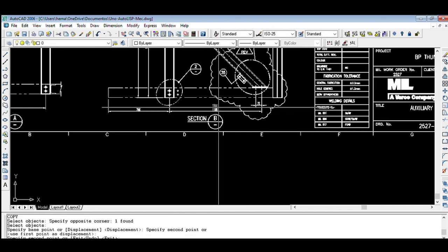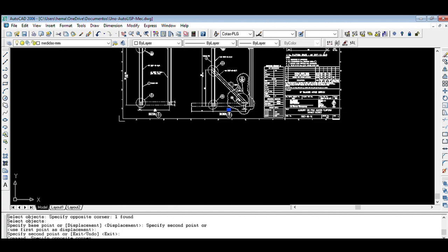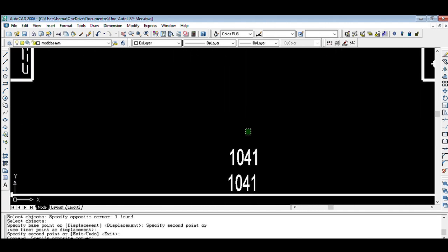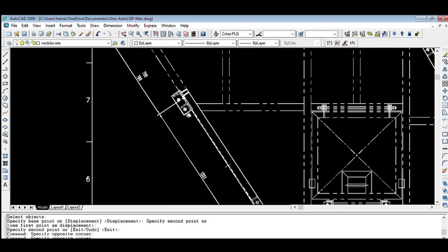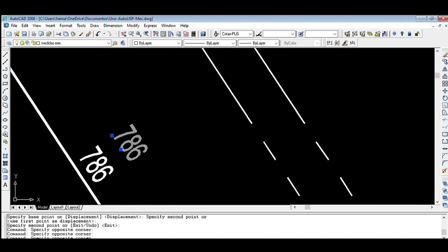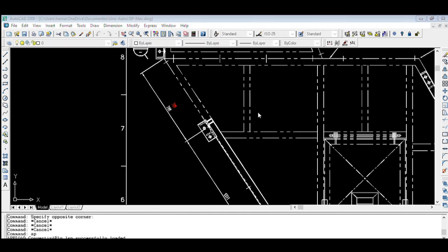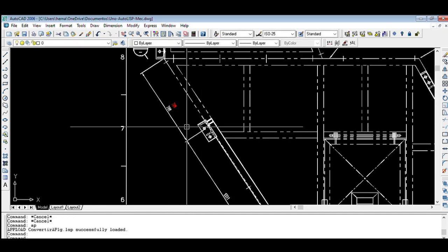I will place those 3 dimensions I copied on layer 0 and give them a red color. Now, we can run the program. I'll load it. I'll type the command, millimeters to inches, but in Spanish. We indicate the layer where the text objects to be processed are located. The result indicates that it processed 45 entities.